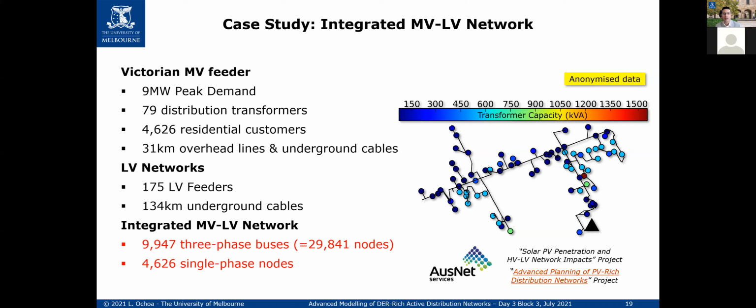So you cannot force your mathematics to solve a problem that doesn't exist, because the actual physical problem is discrete. Now, you can use it as continuous, but then the moment that you take these settings and move them to the real network, you will have a very different output. So why were you bothering so much with optimization when your outcome in the real network is totally different because of the discrete nature of the devices? So it's entirely up to the distribution company to accept those challenges and say, yes, let's do the OPF in a continuous way for these elements, and we accept the fact that we will never have the values that the OPF is telling us in terms of voltages or whatever it is that you're able to maximize or minimize, because the settings going to the devices are discrete and they will never achieve what the OPF wants. It's entirely up to the distribution company to decide that that's acceptable or not. So that's the answer there.